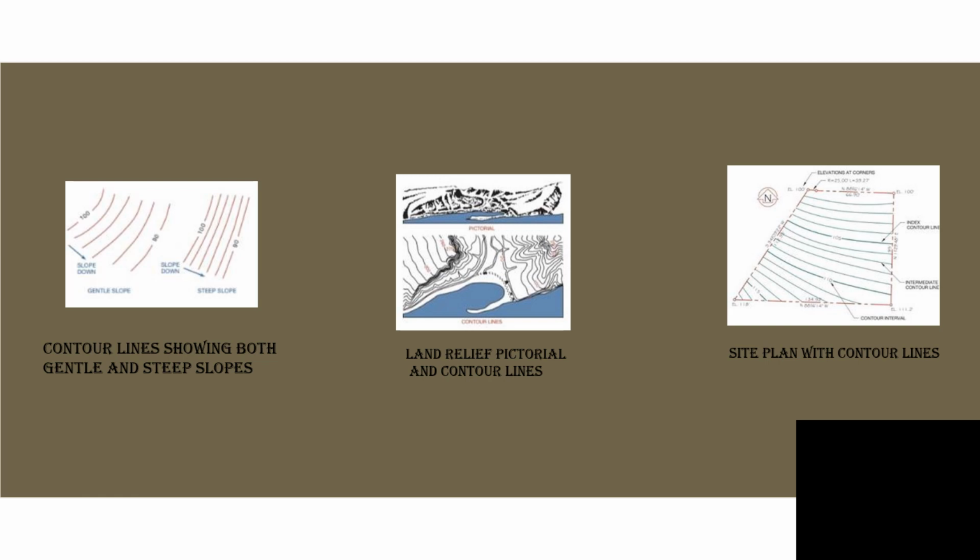Site plans do not always require contour lines showing topography. Verify the requirements with the local building codes. In most instances, the only contour-related information required is property corner elevations, street elevation at a driveway, and the elevation of the finished floor levels of the structure.